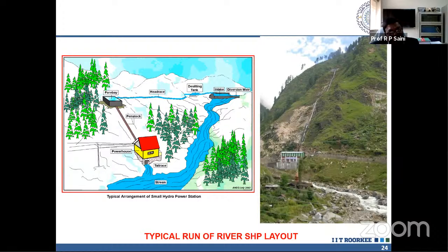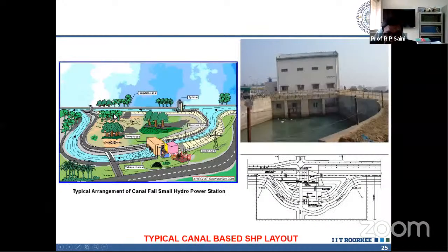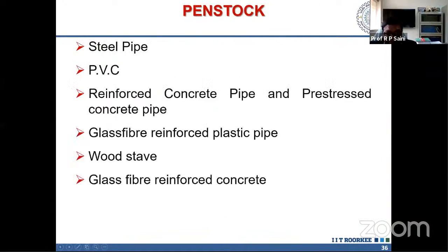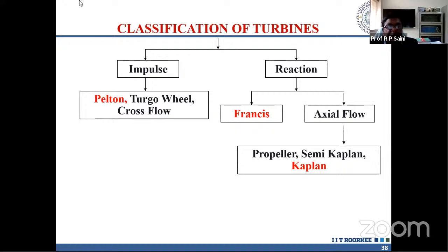That will be the capacity, the volume of the tank. Again, I'll miss many things if I keep on discussing. So the next very important component is the turbine. Quickly, when we discuss power, it is Q into H, the discharge and head. So there are two parameters. If you have a very high head and low discharge, the capacity can be sufficient.